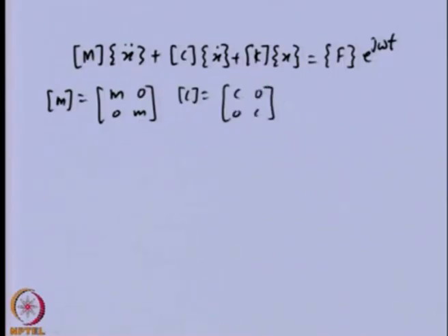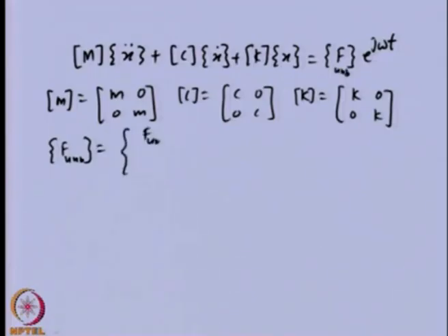And f amplitude and the j omega t time dependent term is outside, where we have a mass matrix, earlier defined as like this, damping matrix as this, and stiffness matrix K. Diagonal terms are there in all of these, and the unbalanced force: this particular unbalanced force we have as unbalance in x direction and minus j unbalance in x direction, because this is taking care of the 90 degree phase.